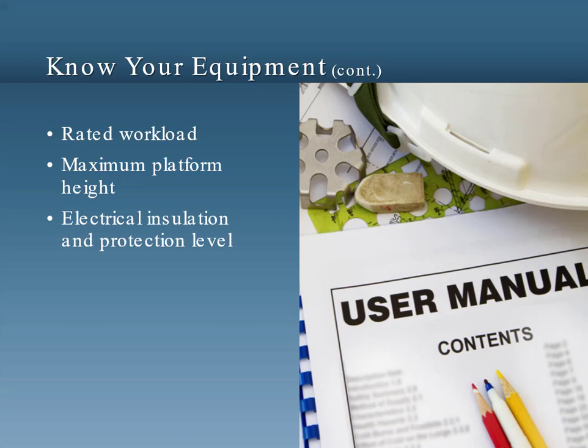Aerial lifts may also be marked with a statement that indicates whether the work platform is electrically insulated, and if so, the level of protection the insulation provides. You should be careful to keep aerial lifts away from power lines anyway, but be extra careful if the platform is not insulated.